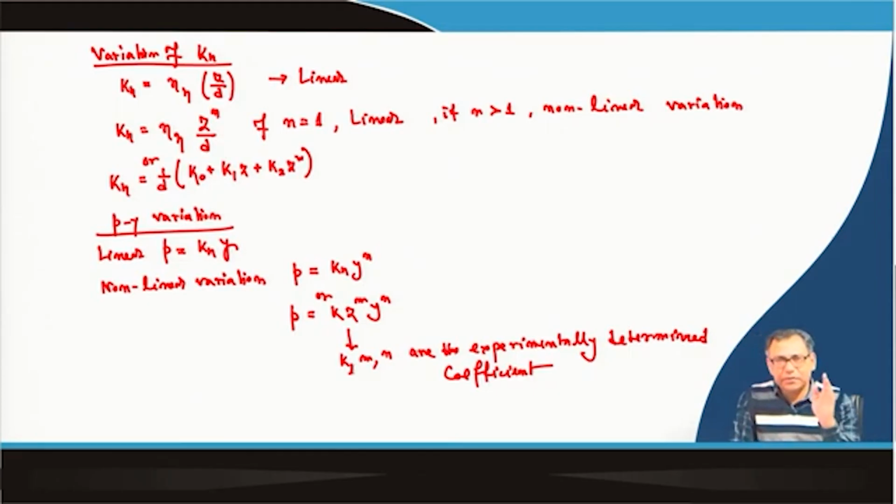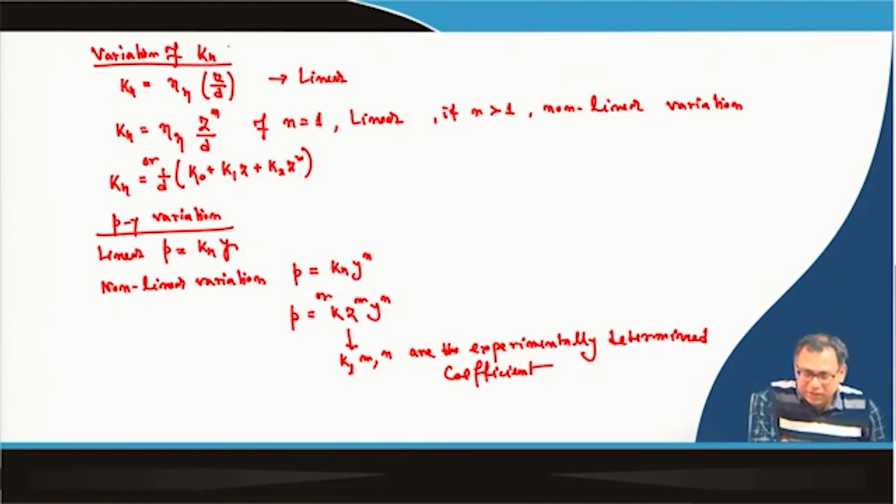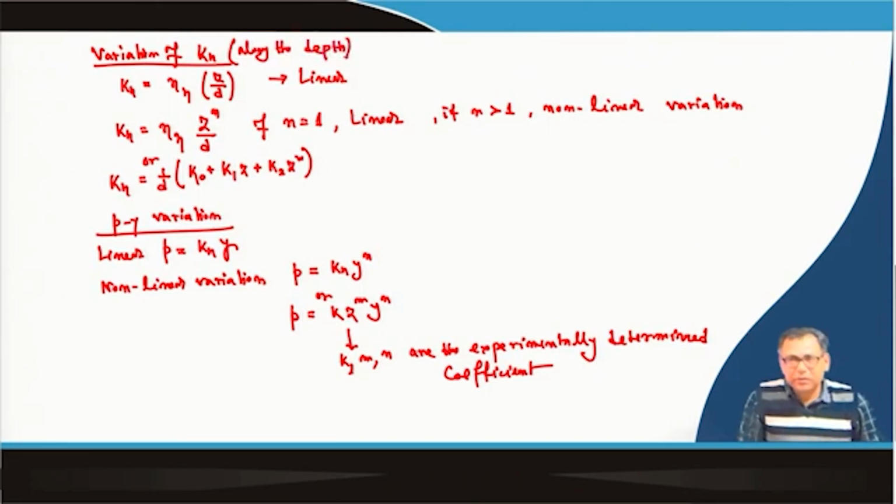So, that means here that beams are not only resting on a linear spring, it can be resting on a non-linear spring also. That means you can incorporate the non-linearity in the load deformation behavior. You can put the non-linearity in the variation of the kh along the depth. So, that we can incorporate in this equation and then we can solve it.